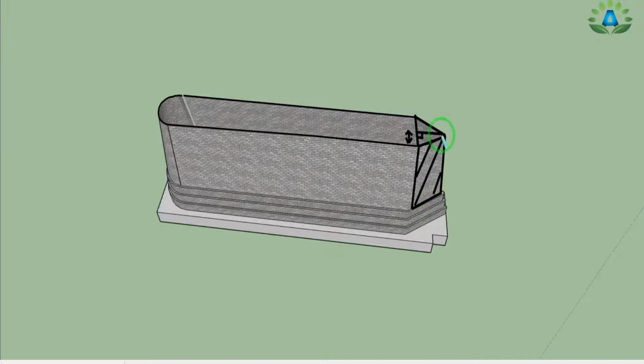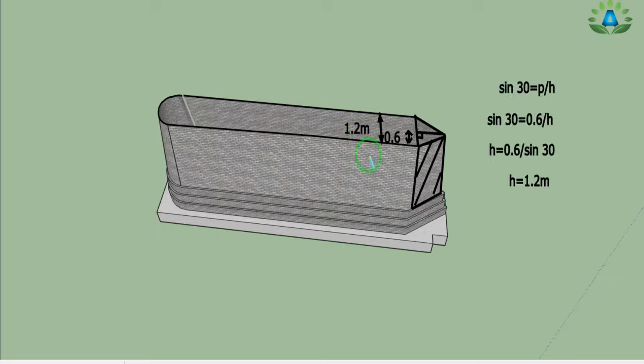To calculate this incline length we need to use the trigonometric relationship of sine, because we have this total width. Here we have the width at its midpoint, 1.2 meter, that is the average of 150 centimeter and 90 centimeter, and we have this angle 30 degree, and we know that this length equals 1.2 by 2, that is 0.6 meters.